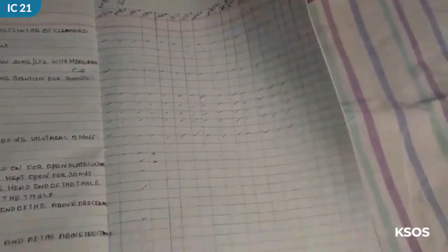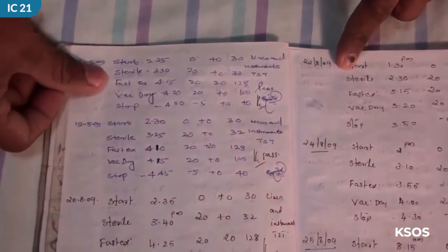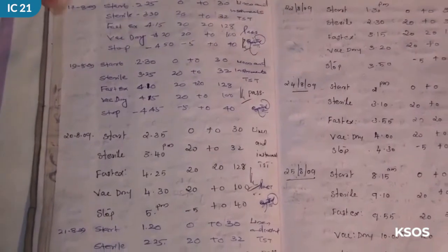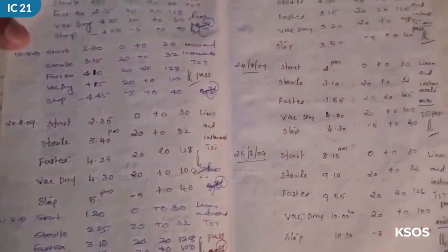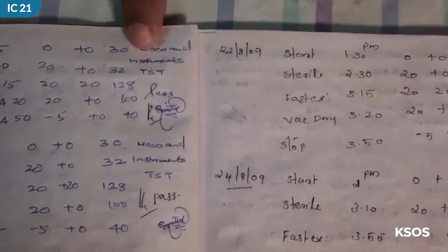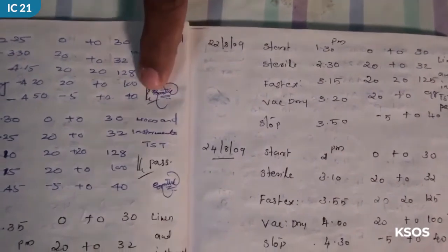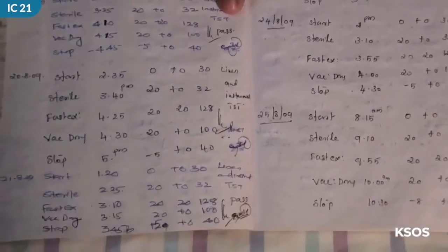And it should be countersigned by the medical officers. The autoclave units should be recorded. The start time, the vacuum time, and the steam holding time should all be monitored and registered. Now we have automated machines which record all these procedures by themselves.